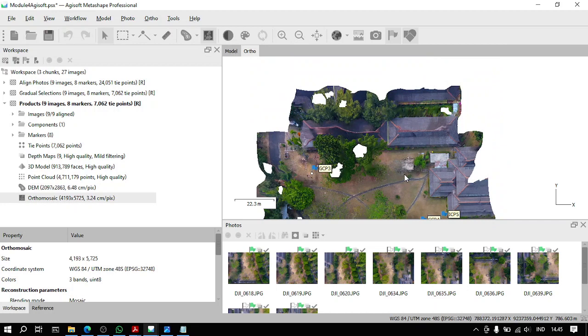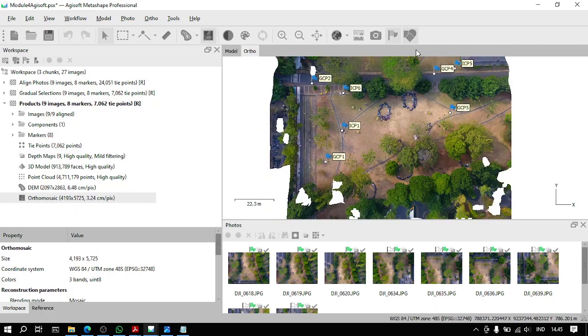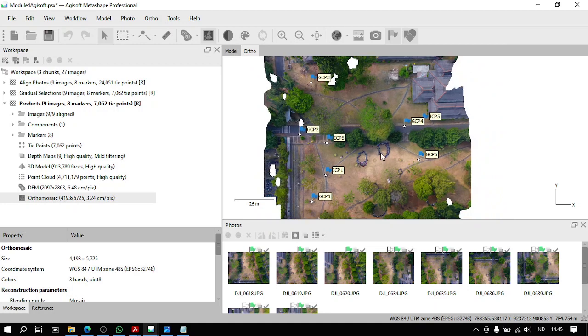You know there's a pattern here, right? The more on the edge, the more outside the point is, the more distorted the image would be. So I'm going to give you a clue here. The best quality for any aerial photographs is between the control points.